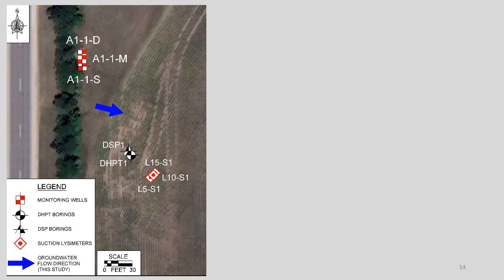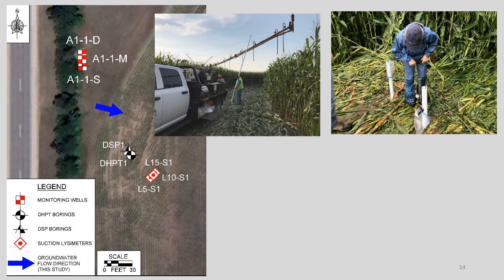There were indications in the literature there could be a clay layer that might affect interpretation of the results. And we also sampled groundwater at high resolution below the water table. There were already existing conventional wells: a shallow water table well, a medium depth well, and the deep well would have been about 80 feet.